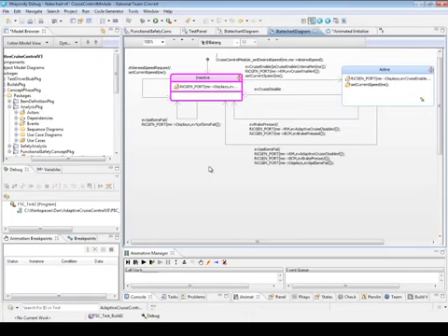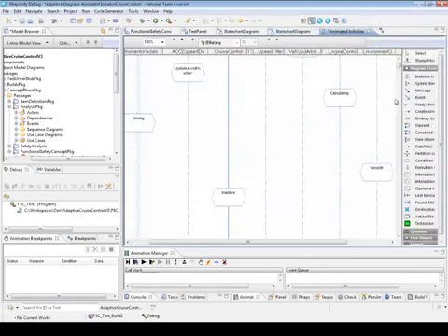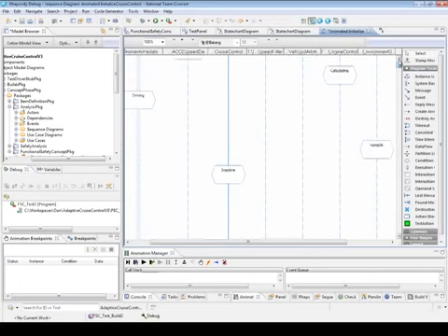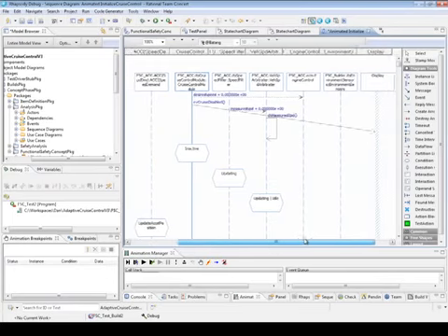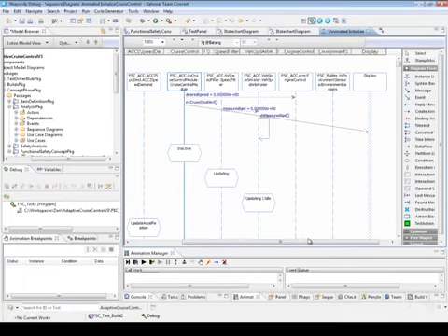In this state chart, at the moment we're in the inactive state, but we will go into the active state later on. If a sensor failure is detected, it will then go from an active state into the safer inactive state where control is returned to the driver. As we're going through our scenario, the sequence diagram will actually record all the inputs and outputs as they occur between the various elements in the model.